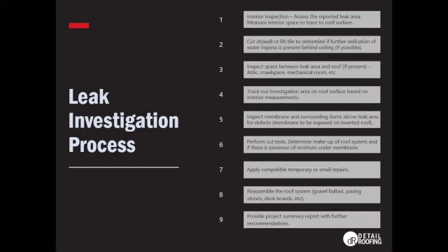If there's any sort of attic space, crawl space, mechanical room, basically anything between the leak area and the roof, if possible, we always want to access those areas to see if there are any other signs that can help diagnose the issue. On the roof, we trace out the area, complete a membrane inspection, and check any surrounding penetrations.